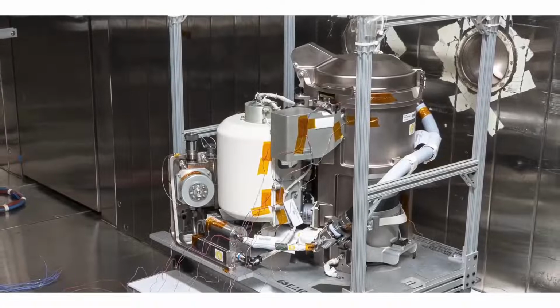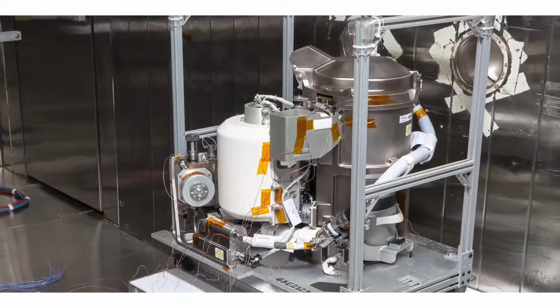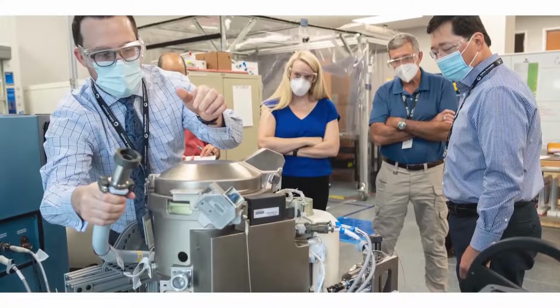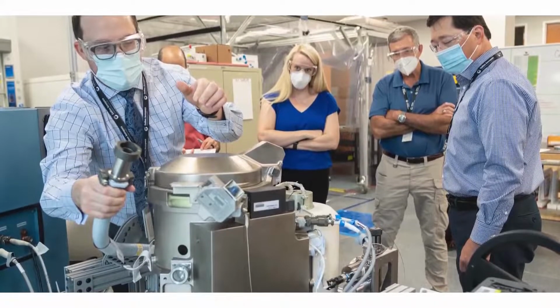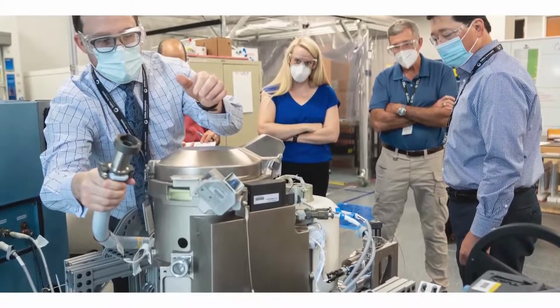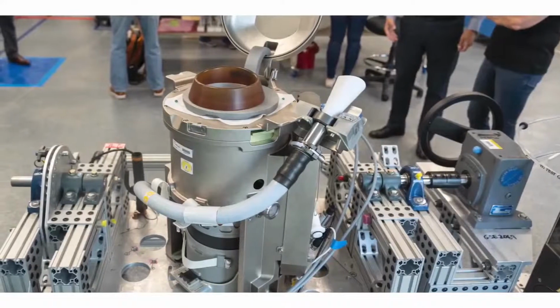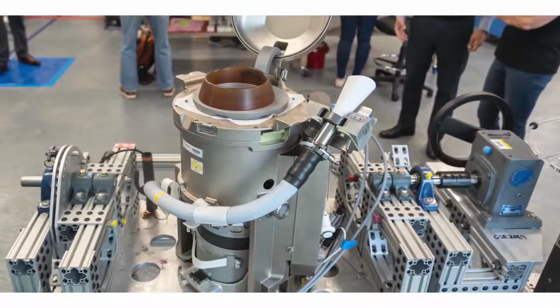65% smaller and 40% lighter than the current toilet used on ISS. Our toilet will be installed just adjacent to that toilet and will undergo a concurrent use with that toilet as we do the demonstration. One of the things the UWMS has to do is it actually has to inject pre-treat into the urine before it sends it to the urine processor assembly. The pre-treat is a very strong acid, and it is not very compatible with a lot of materials, so that forced us to have to use a lot of exotic materials such as Inconel, Elgiloy, titanium.